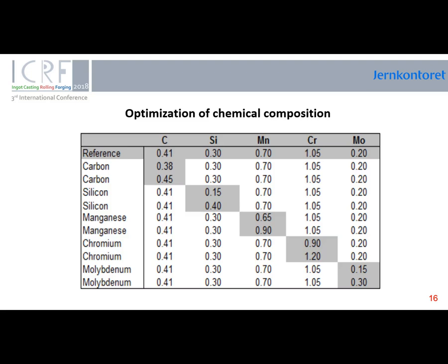To analyze the influence of chemical composition on A-segregation, the elements that have been taken into account are in this table. The ingot size and shape are like in the other experiments, and the pouring temperature has been 1570 Celsius.